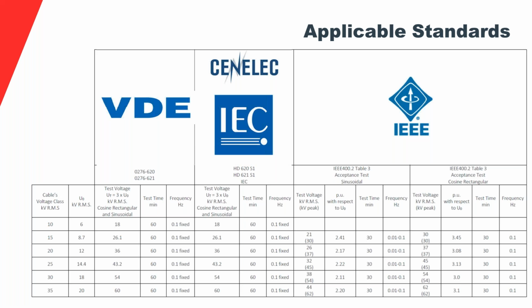If you have an aged in-service cable with some water treeing, will VLF accelerate the minor water treeing, or will the electrical treeing not affect the water treeing? Or the likelihood that the water tree will now form the electrical tree? Okay, so the way this works is, again, the acceleration happens only to the electrical treeing. The water trees are not affected. They grow by themselves in service.